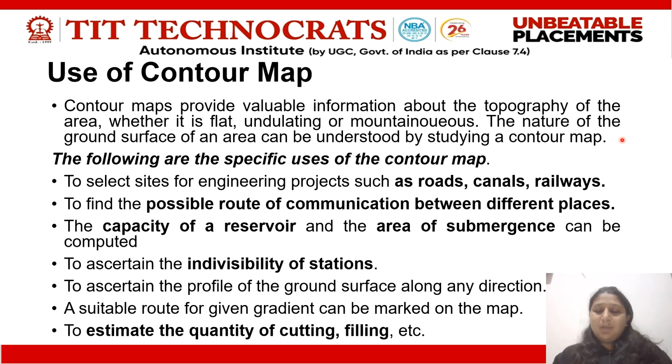A question may arise in your mind: ma'am, you're explaining contours and contour lines, but what is the purpose of this topic for an engineer? So here are a few specific uses which I have mentioned. The very first and very basic use is that we need to know the earth surface level for various construction projects such as roads, canals, and railway lines. For this, we need to understand the topography of that area. The contour maps prove to be very essential and useful.